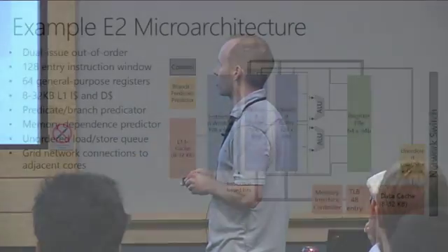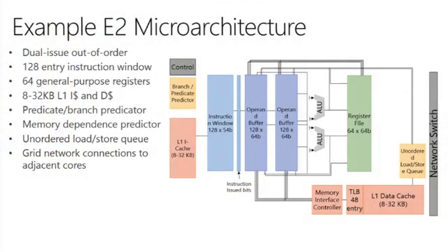Okay? Again, this is not new stuff; we've been working on this a long time. But now in a microarchitecture, you have your caches, which is a fairly standard thing. Now you have an instruction window, but rather than a centralized register file, you have one for the begin and exit of a block. You now have buffers to hold the operands being produced for each instruction. An instruction issues with a pointer to a buffer slot, and it will just write the results in there.